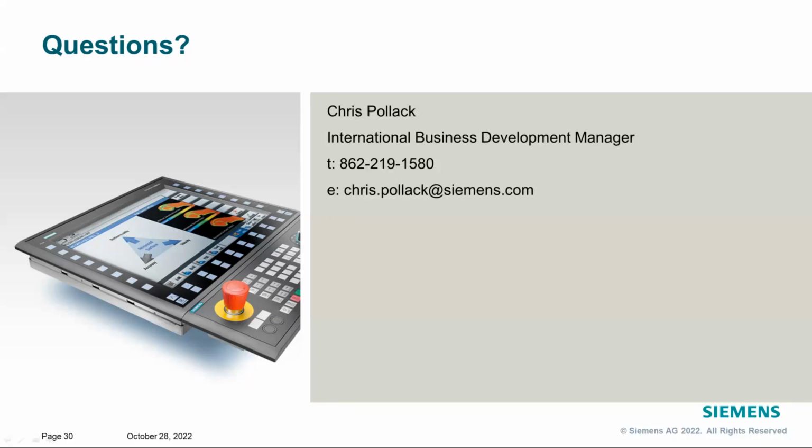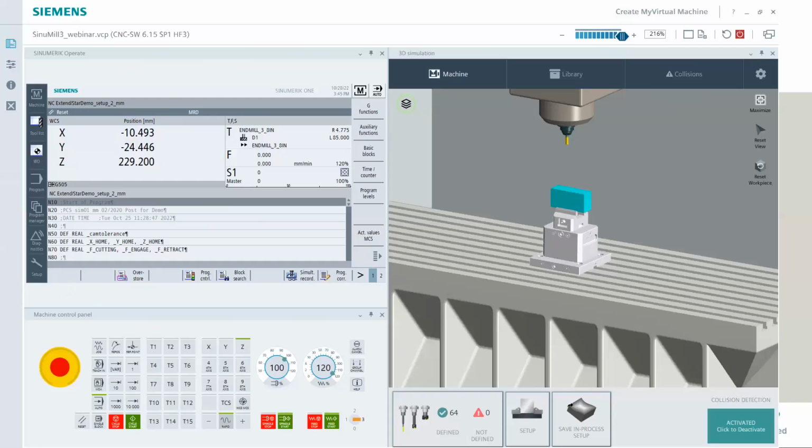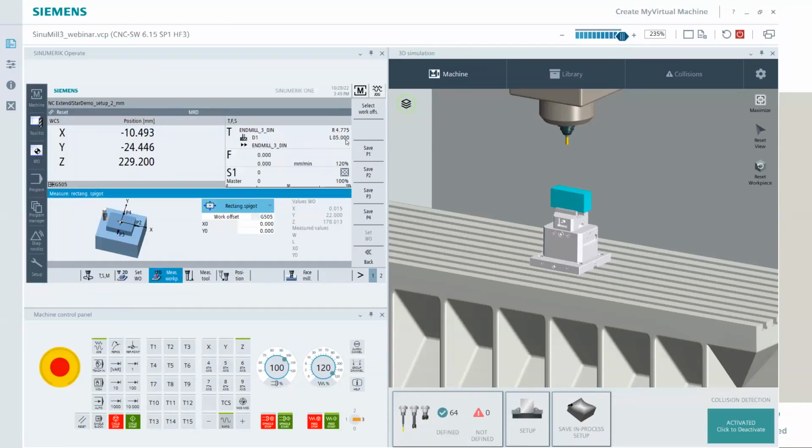Is there going to be a calibration of a sphere added as a default option? So the sphere is already there, right? Let me just show you guys real fast. Paul is asking, when I go to calibrate, let's go on to jog. Back out of here, we have an option for a sphere. If I had built a sphere and it was on my table, I could absolutely calibrate to a sphere. I just calibrated to a ring because that was what was in this machine. But I could have made my tooling ball sphere as an STL, dropped it in the table, put it in position, and calibrated my probe that way. For sure, that would work.